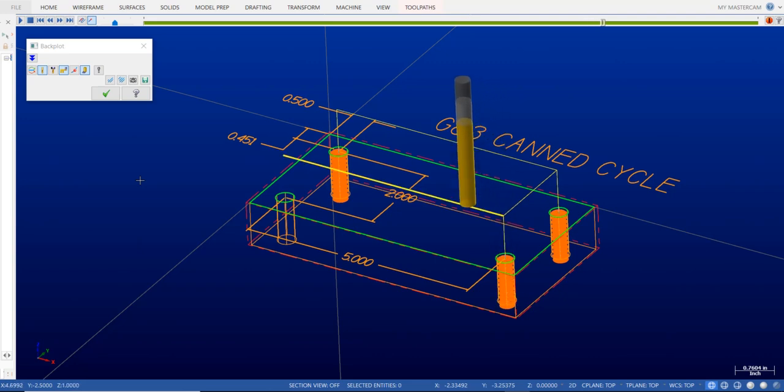Alright, so we're drilling a 5/16 minor diameter hole, and we're drilling all the way through this 1-inch thick part, and then we're going to be tapping it with a 3/8 tap. But first of all, let's take a look at the code, and we're going to add it to our existing program.